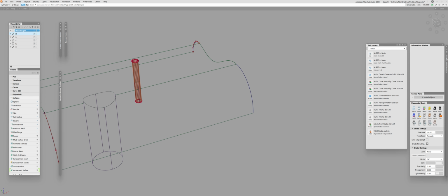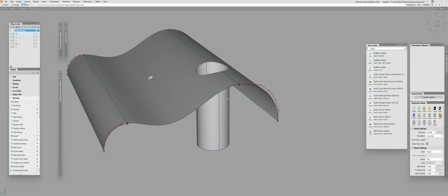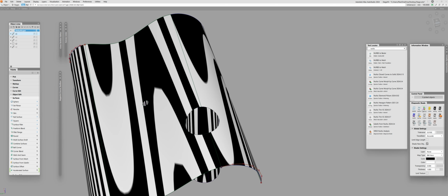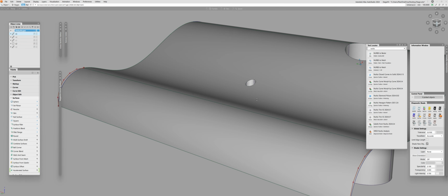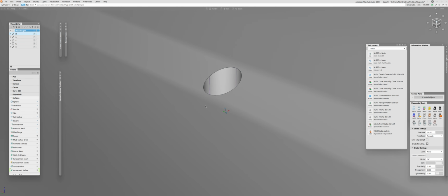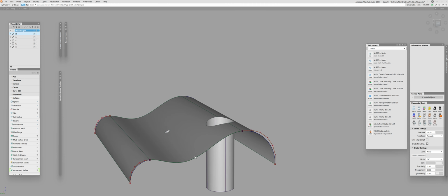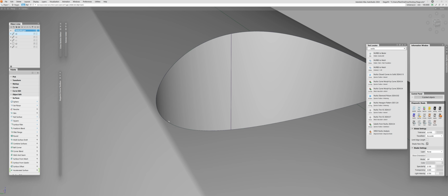So here is another example. Now here I have two circles and a transitional surface with curvature, and if I activate my default shader once again, zoom in, I will see the same issue. These visual issues may be more or less prominent depending on the curvature of your model. Once again, it curves only in one direction, and in this one it's flat. That means we don't have enough supportive edges to fix it.